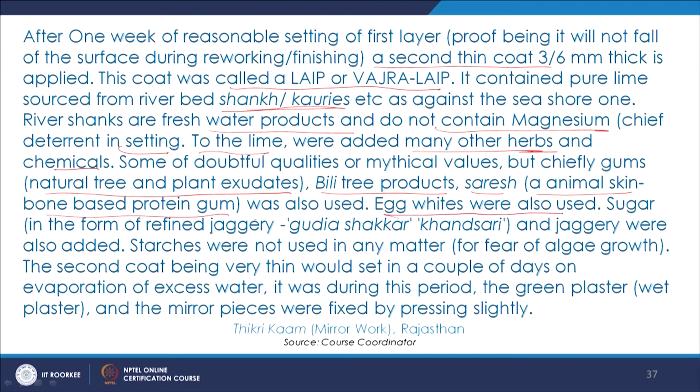Egg whites were also added. Sugar in the form of refined jaggery, which was called gudiya shakkar or khandsari, and jaggery were also added. Starches were not used in any matter for fear of algae growth. The second coat, being very thin, would set in a couple of days on evaporation of excess water. It was during this period that the green plaster, the wet plaster, and the mirror pieces were fixed by pressing slightly.